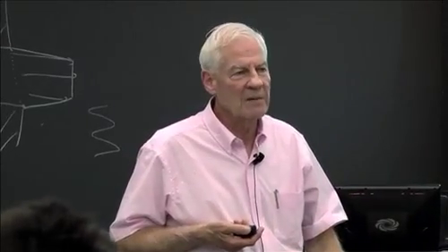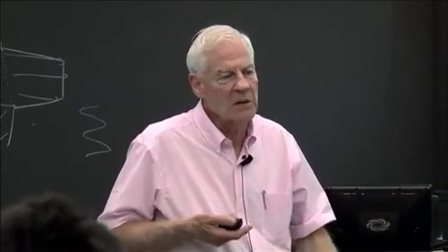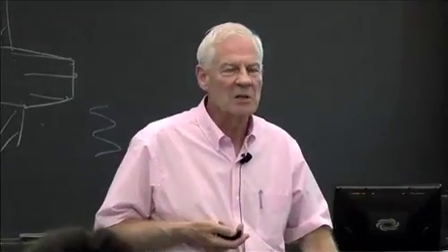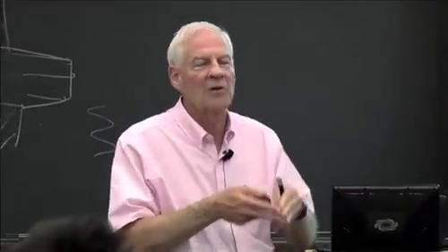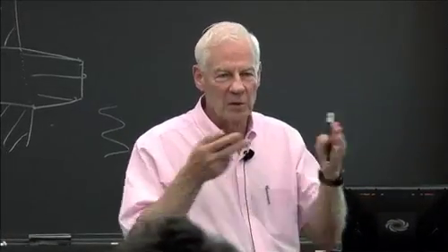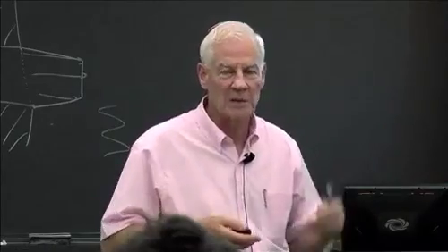So that is nice and simple. As long as the line shape is staying constant, it's got a simple interpretation. So we usually either do fixed wavelength or scanned wavelength. Those are the two. And we either do direct absorption or WMS. Kind of like four possibilities.